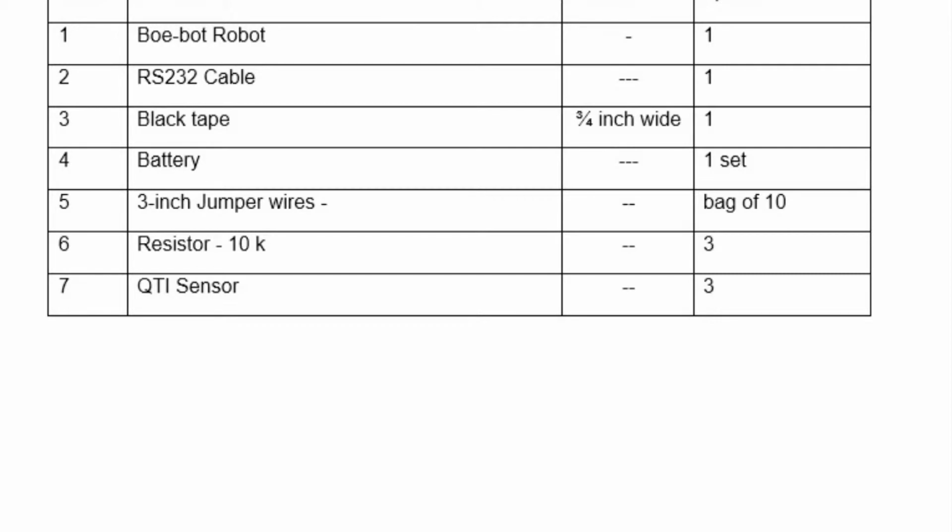And second, we need an RS-232 cable to download a program from a computer through the serial port connector. Third, we need 4 AA batteries to power this mobile robot. And fourth, we need a computer with Basic Stamp Editor software to download the program from the computer to the microcontroller. To program the BS2 microcontroller, we are using Basic Stamp Editor software.